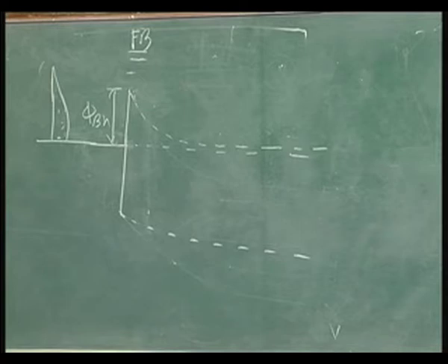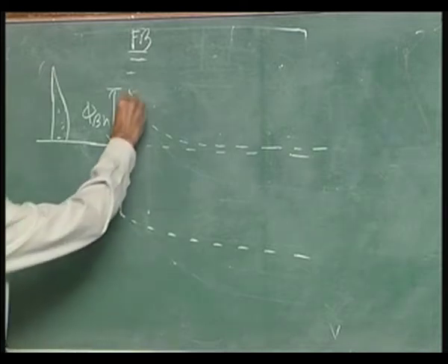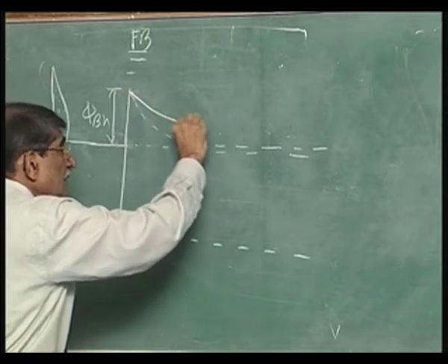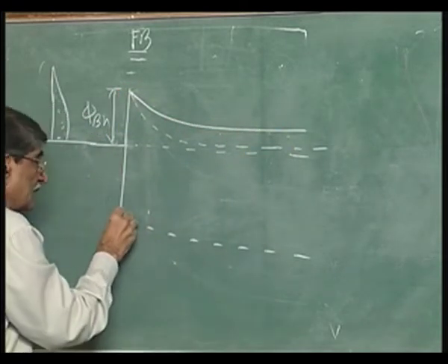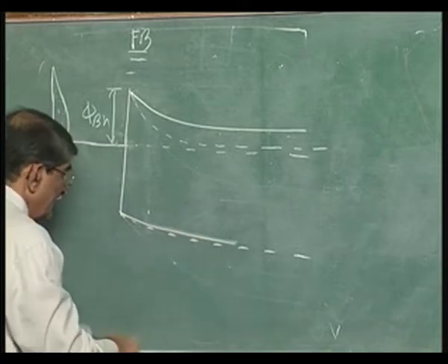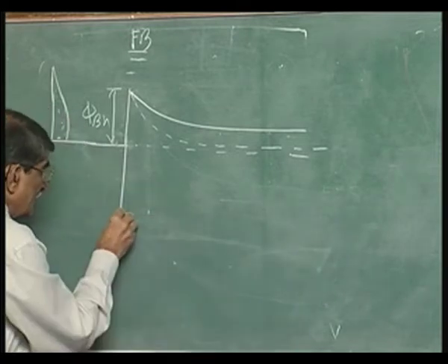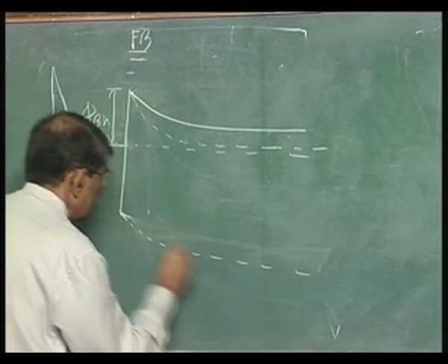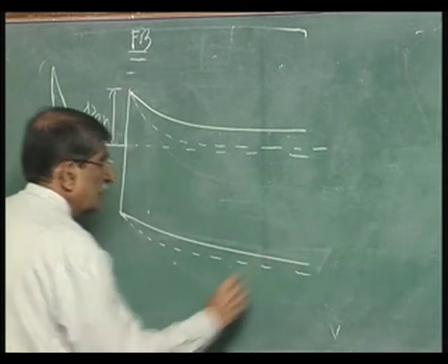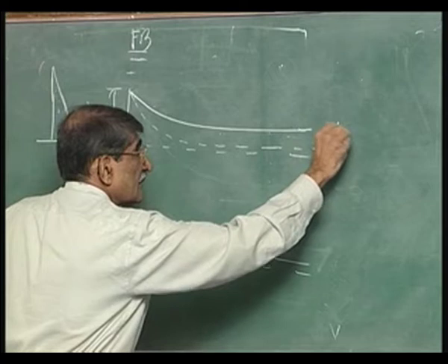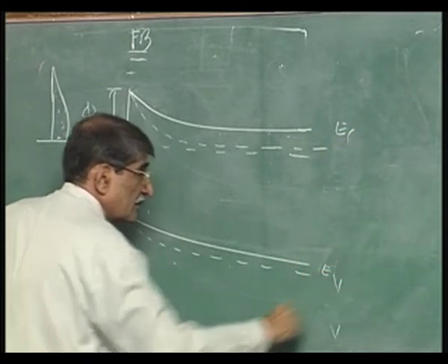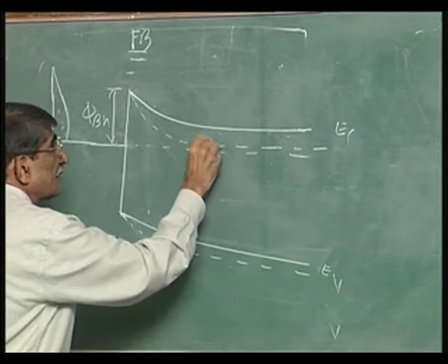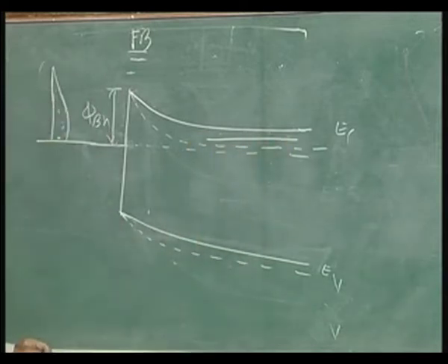So, whatever this Fermi level was, equalized, that whole thing will now move up exactly opposite to the reverse bias. So, this will now go like this. Let me just draw that bit. EC will go up from thermal equilibrium, EB also will go up, and I can draw the Fermi level up there. That is a new diagram.